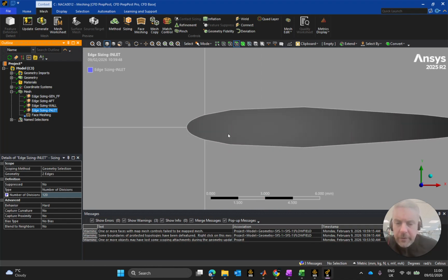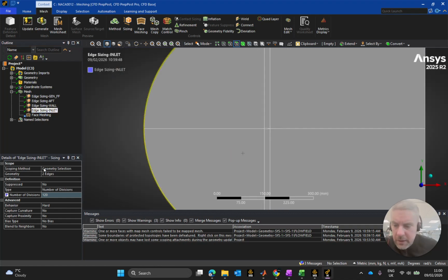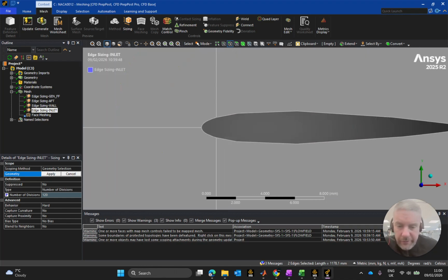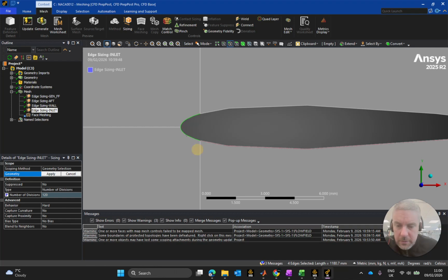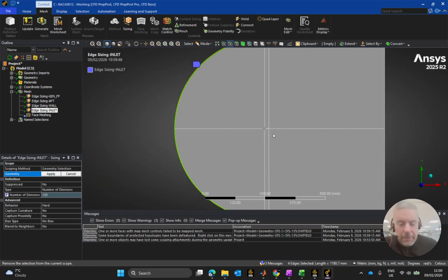On my airfoil I have my 2 inlet faces selected here. I just took it for granted that when something was selected, what was selected was correct, incorrectly. So make sure I've now selected 4 of them, including this one and this one. What had happened there, the non-mapping came in because it had information on one side, but it didn't know really where it was running to.